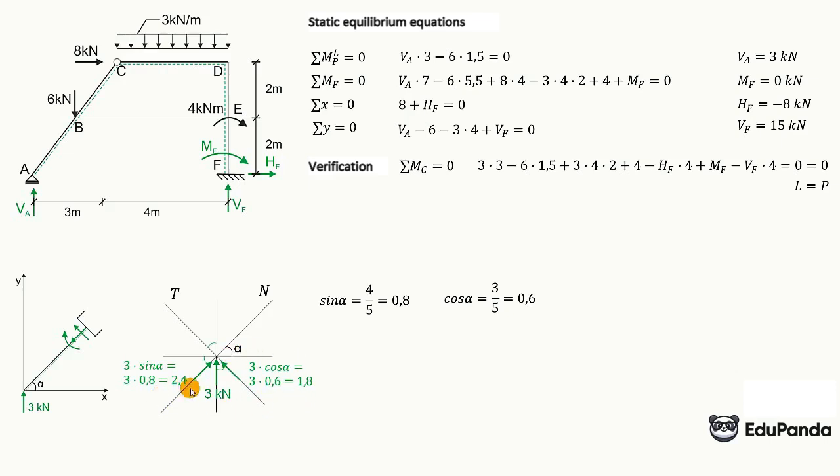I usually don't draw this on the drawing I make here, but somewhere next to it. And now for this drawing, we can apply the same procedure to the second force, which we will also need to decompose because it is on a slanted bar. So in the same way we place it, we have the cutting direction, the normal direction,